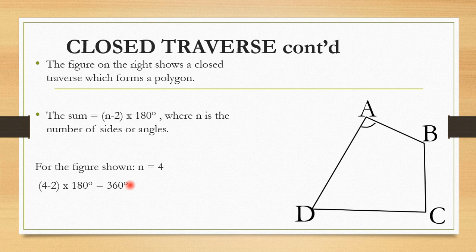Of course, you don't have to do adjustments for just any traversing exercise. There is a limit for that. If the error goes up to 1 degree, then it is good practice to redo the traversing. Otherwise, the whole exercise was a mess.